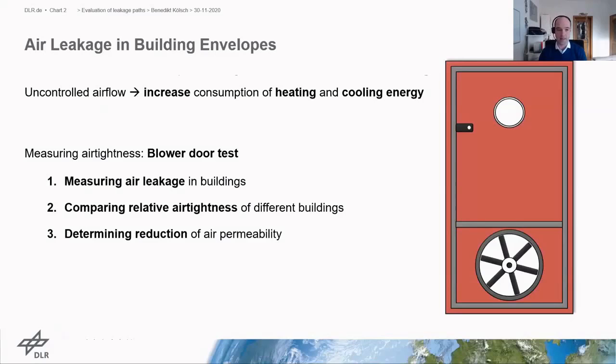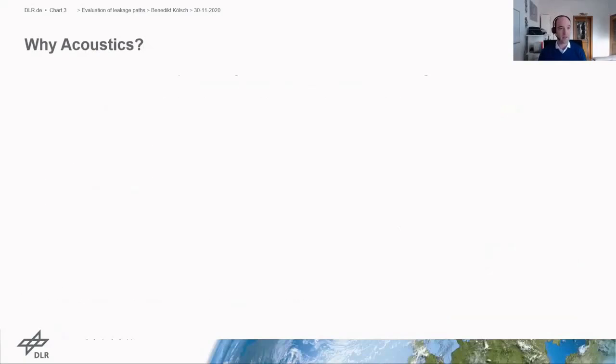But leak detection is very time consuming and heavily depends on the inspector who's doing the measurements, and quantification of single leaks is very cumbersome in buildings. So we are going to investigate supplementary methods for the leak quantification, but we will still have these blower door tests as a basis for the subsequent analysis and as a comparison in this presentation. So we are going to investigate acoustics.